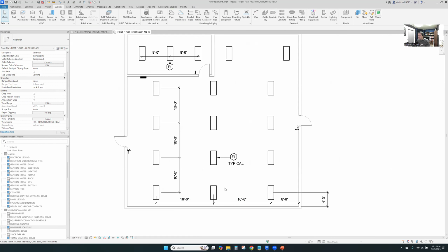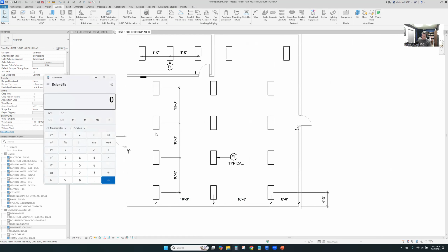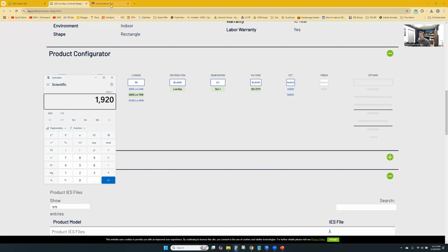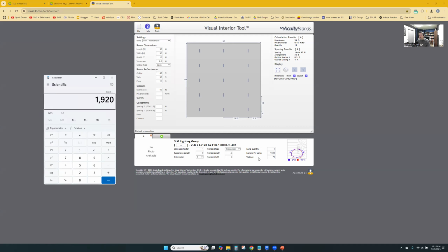So we have here, since 20 times 0.8, so a 20 amp breaker, 80% of it, we can only put 16 amps on the circuit, times 120, it gets 1920 VA per circuit. Then we look at our 73 watts per fixture, so we divide this by 73.